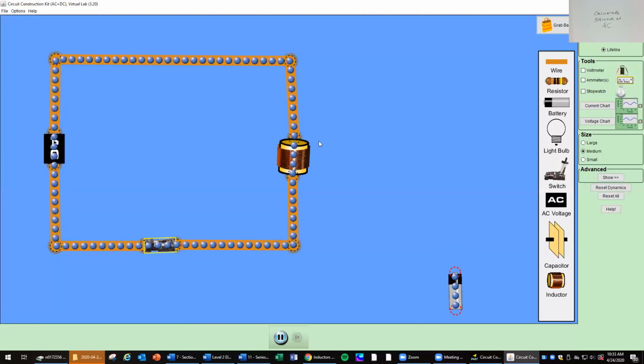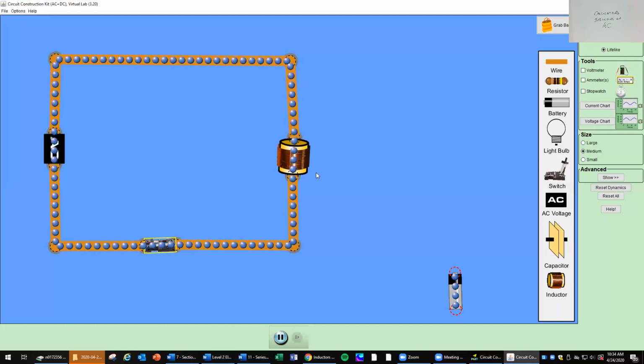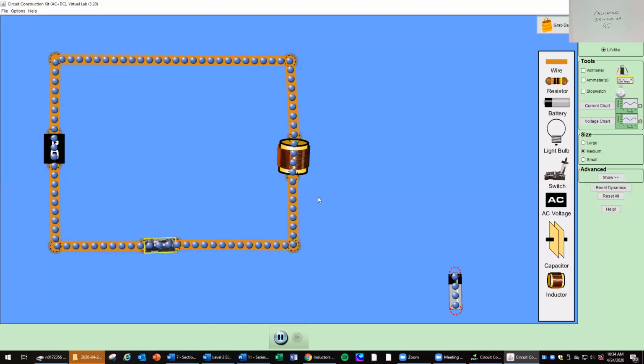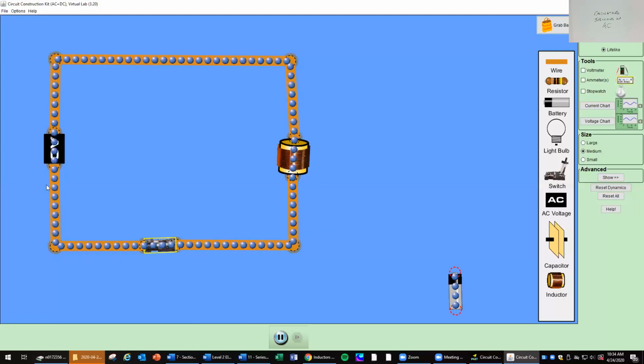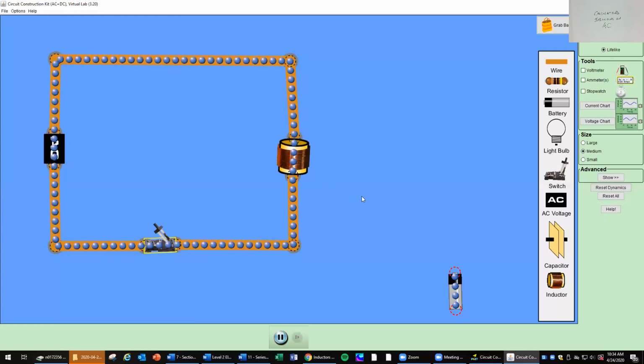But what ends up happening is the inductor has counter EMF that's opposing this change in current flow direction 60 times a second on a typical AC system. And so it does like this shifting back and forth because it's an AC circuit. And it will start to shift more into the upward direction or counterclockwise given enough time. So what I want you to realize is that this is offering some form of an opposition to current flow, which sounds very similar to what we have with resistance, which is an opposition to current flow.